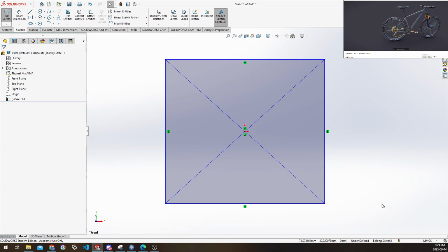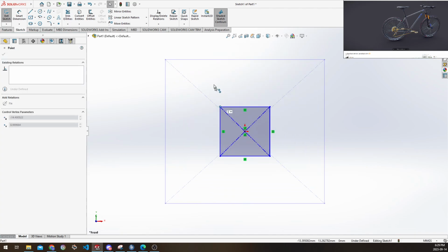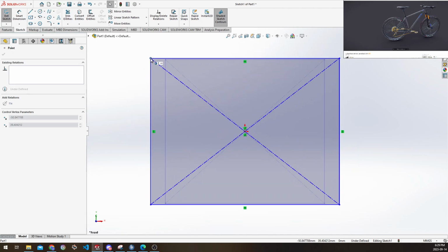First thing, as I mentioned in the classroom last week, is to always check whether your parts are defined or not. In the bottom right corner, you can see I have this message here. It's kind of hard to see, mixed in with all this other stuff, but you can see it's underdefined. In this case, we're underdefined because the size, the scale of this object, is not yet defined. The shape of this is defined in vector space, but the size of it is not. Either way, it's still a rectangle.